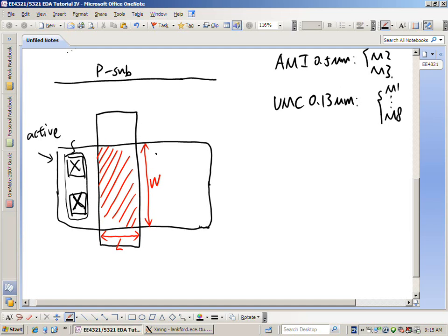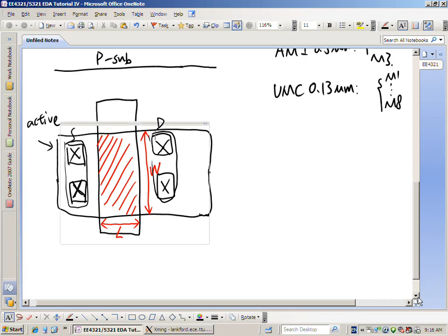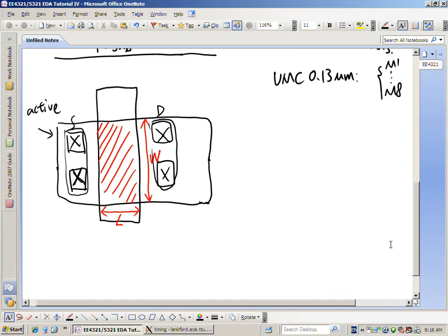And on the other hand side, I can make contact for my drain, like this. So pretty much this is what we have for the transistor. However, we still have to route out the signal for the gate, right? Normally we don't make contact directly above the gate.